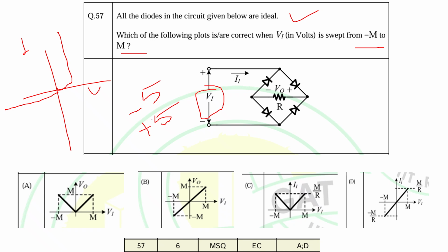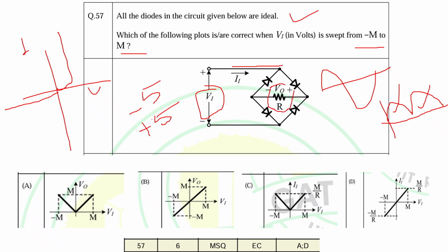So before going ahead, let us discuss how exactly the current will flow through this rectifier. Suppose there are two cycles, positive cycle and negative cycle. Of course, the output will be something like this. Here both cycles will cross, right? The positive cycle will be positive only, and the negative cycle will also be reversed, and the output that you will observe across the resistance will be similar to this waveform, positive only. So that is called the full wave rectifier.